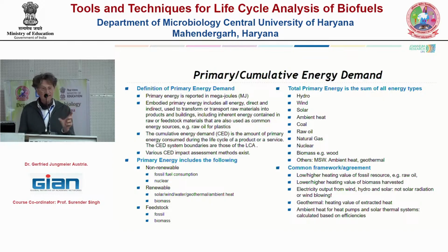Finally, there's one distinction: the primary energy. I think in America, I don't know how it is in India, but in America, normally they calculate with a higher heating value in all of their calculations. We in Europe, and I don't know how you handle this here in India, we always calculate with the lower heating value. And the difference is only the energy from the water vapor you create when you burn something. And so also for the primary energy demand, you have to say I'm always referring to the lower heating value, or I'm always referring to the higher heating value.